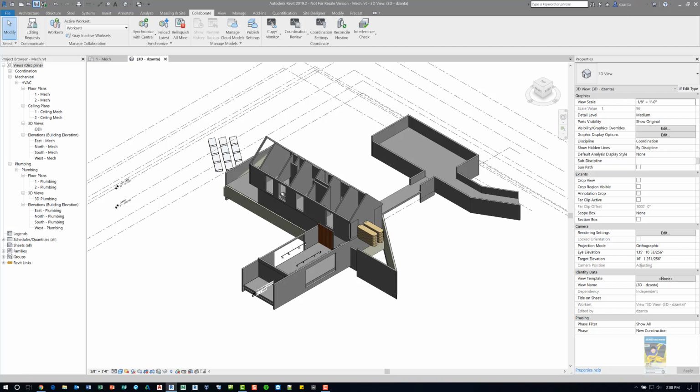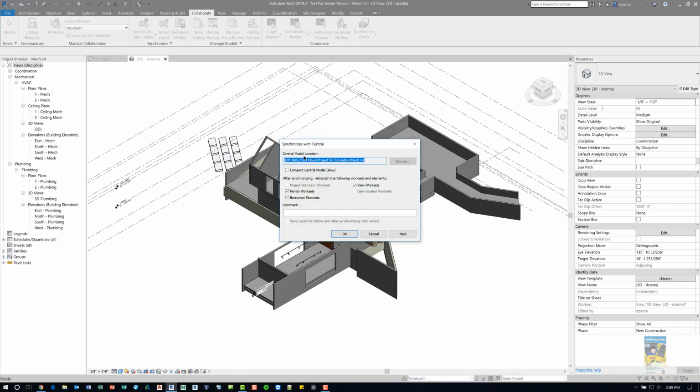And save it back to Central by clicking Save to Central. This will upload the data to the cloud, to your hub, to your project, to your subfolder that you told it to. Okay? So let's go ahead and let it finish saving to Central. And you'll see again that it's pushing up to the cloud, and I'll click OK.